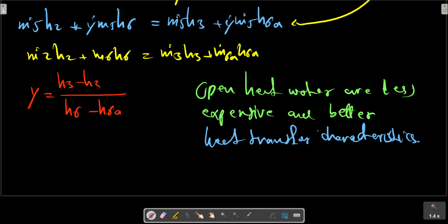They have the disadvantage of requiring a pump to handle the feed water between each heater. In many power plants, a number of extraction stages are used, though rarely more than 5. The number is of course determined by economics.